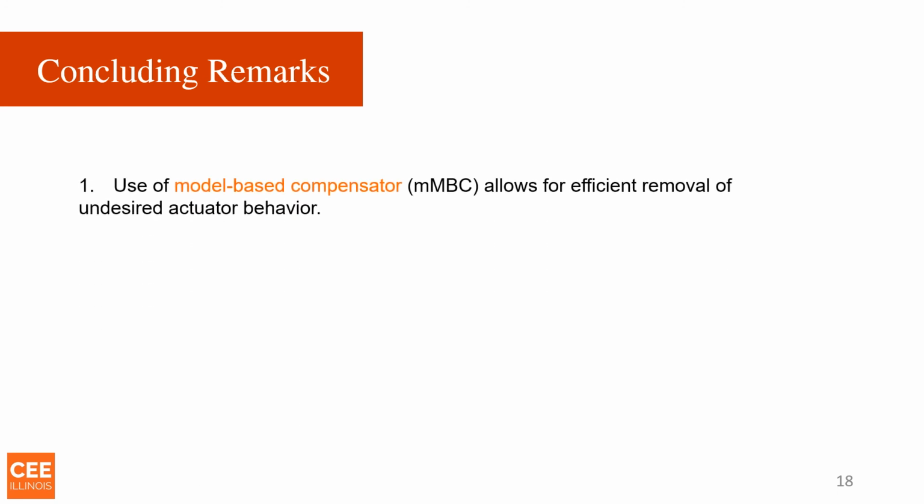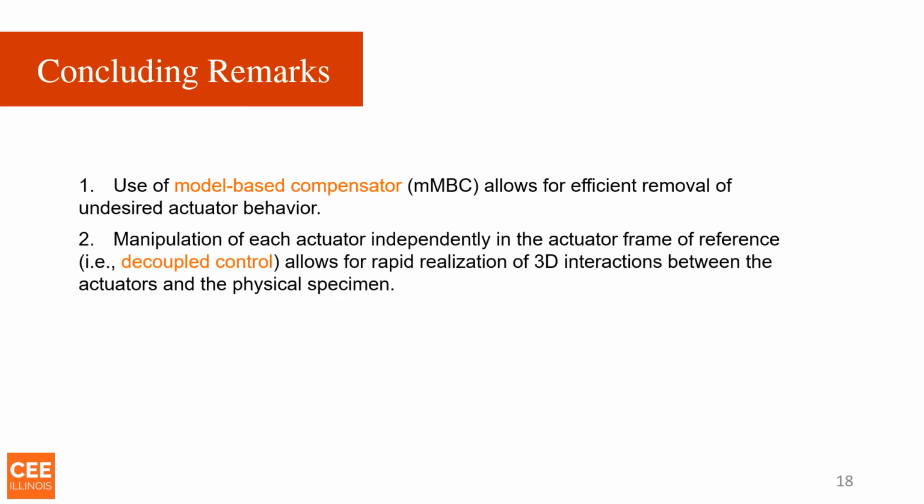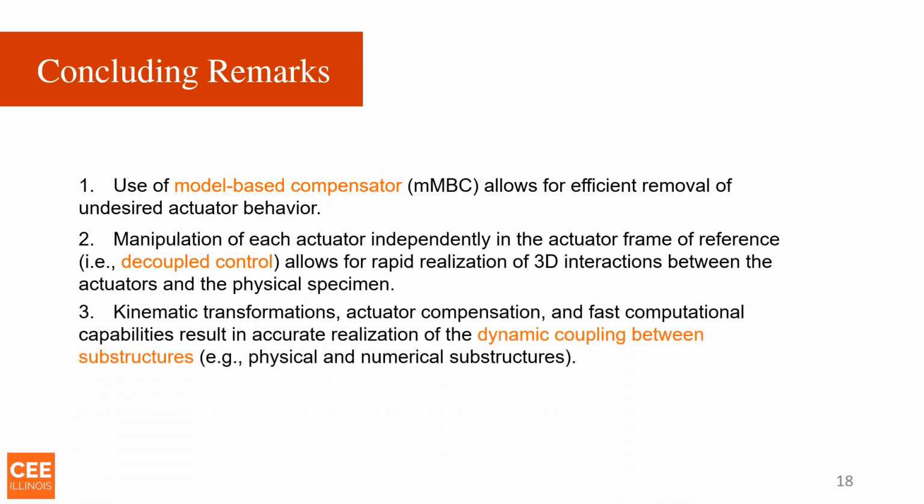In conclusion, we used a model-based compensator to allow for efficient removal of undesirable actuator behaviors. We manipulated each actuator independently in the actuator frame of reference. This was called decoupled control. This allowed for rapid realization of the 3D interactions we were looking for.